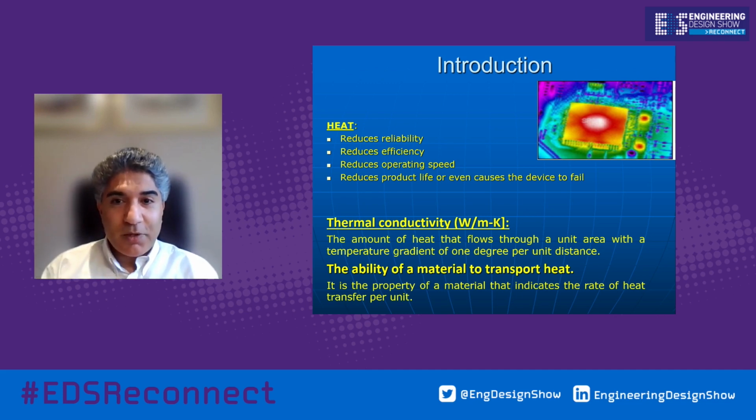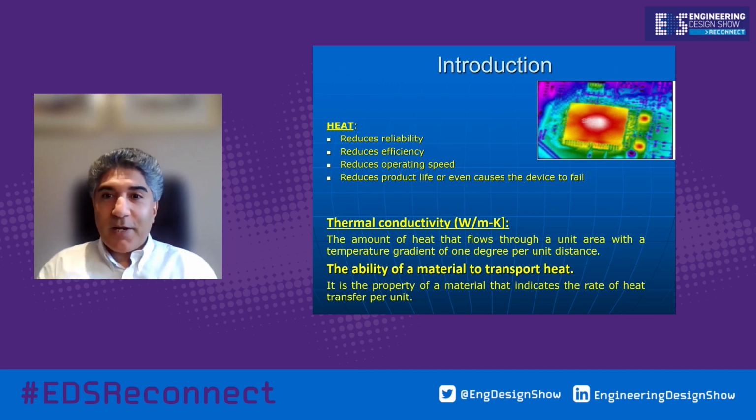On the top right-hand corner, you'll see a microprocessor with greater surface area, the red being the high concentration of heat, normally concentrated in the center of the component. But please don't neglect the smaller components, which have smaller surface area and could be equally of concern and problematic when managing heat.